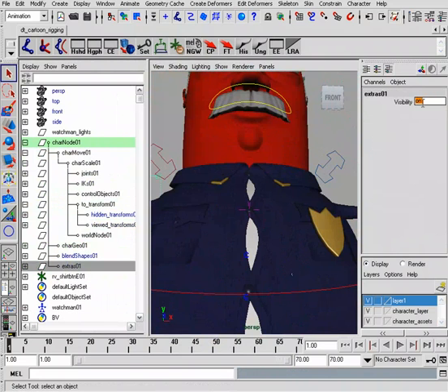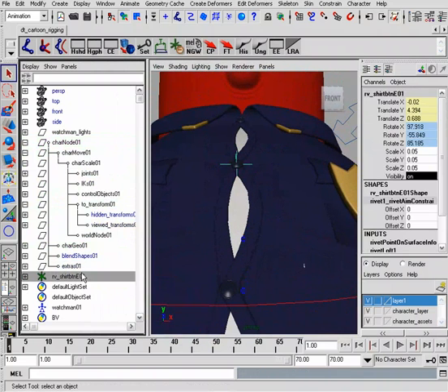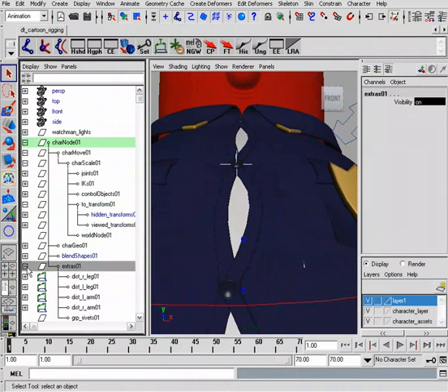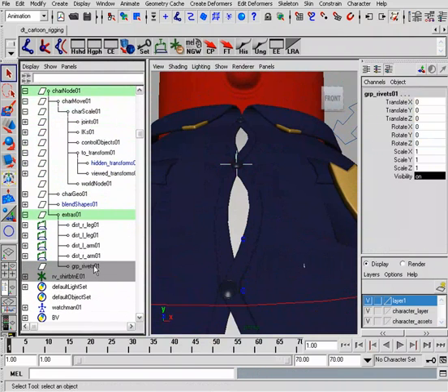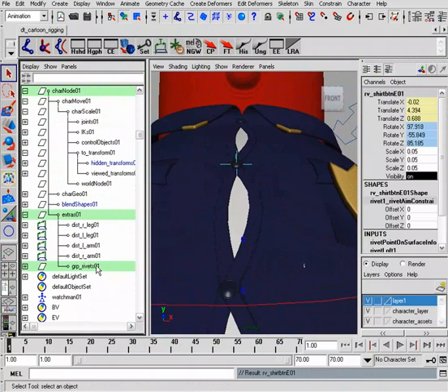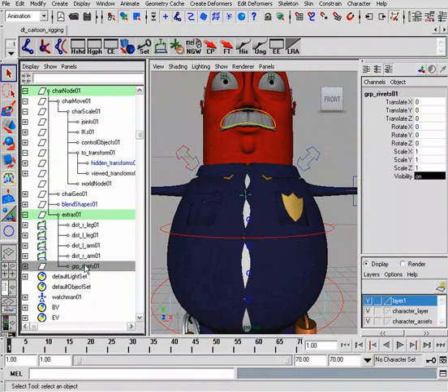So when we turn on extras, now we take our rivet, parent it right underneath our group that we've made. So that's our group rivet. So we'll select the rivet, control click our group, P. Great. Now we just need to make it scale now. Of course, there's no scale applied because it's not under our scale. But rather than applying it under our scale, which we don't want to do, we instead do a connection by a constraint.